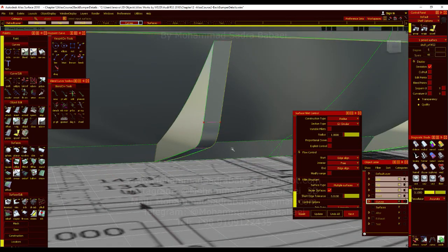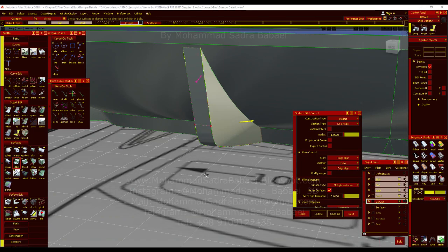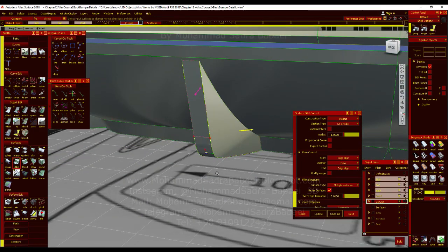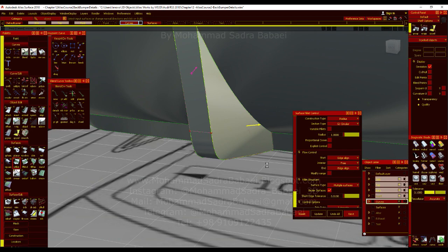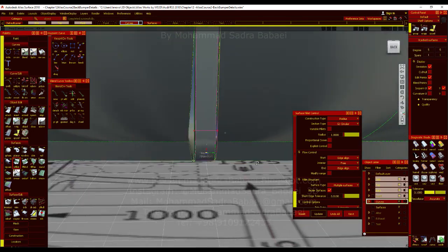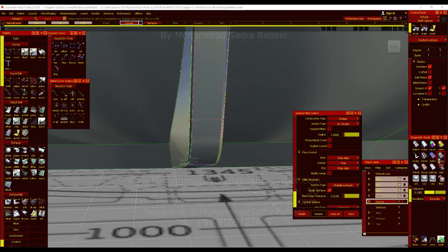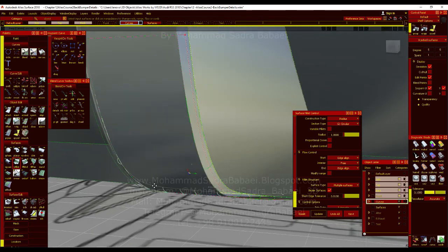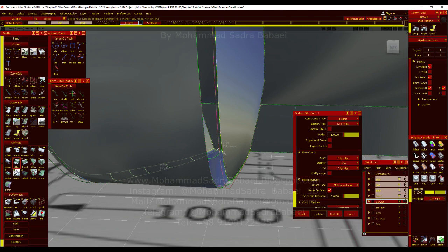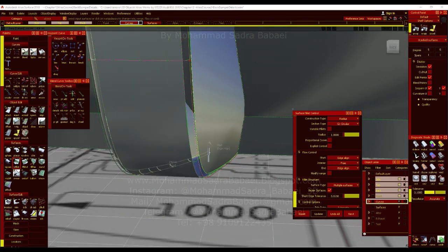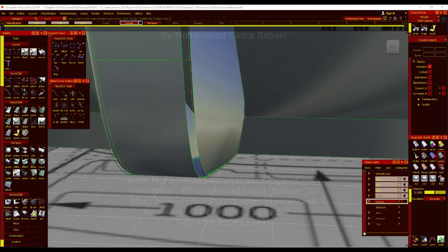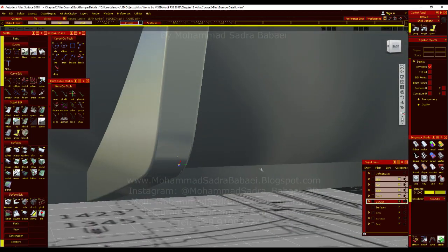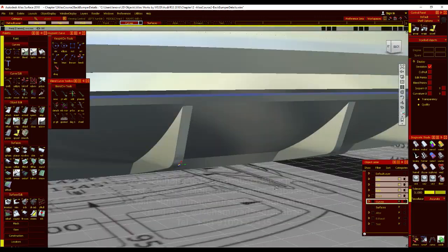Let me try again here. Click on build. Okay. As you see, there are some lines which shows you the fillet is correctly created, so don't worry about that. Just click pick nothing or pick object and click on the shading.